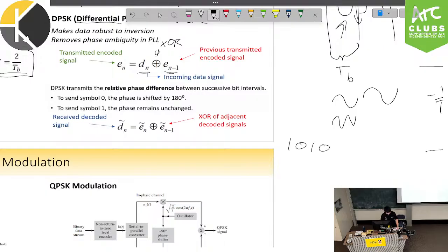Okay, so let's just do a little example. If I have 1 0 1 1 1, and I'm saying, okay, my encoder is going to begin imagining there's a 1. What is the encoded thing going to look like? So it begins thinking there's a 1, it sees a 1, so there's no change, sees a 0, so there is a change, there's a 1, there is a change, there is a change, there is a change, there is no change. So this would be the encoded versus the unencoded, just the incoming signal. Okay, hope that helps. Let's keep it moving.